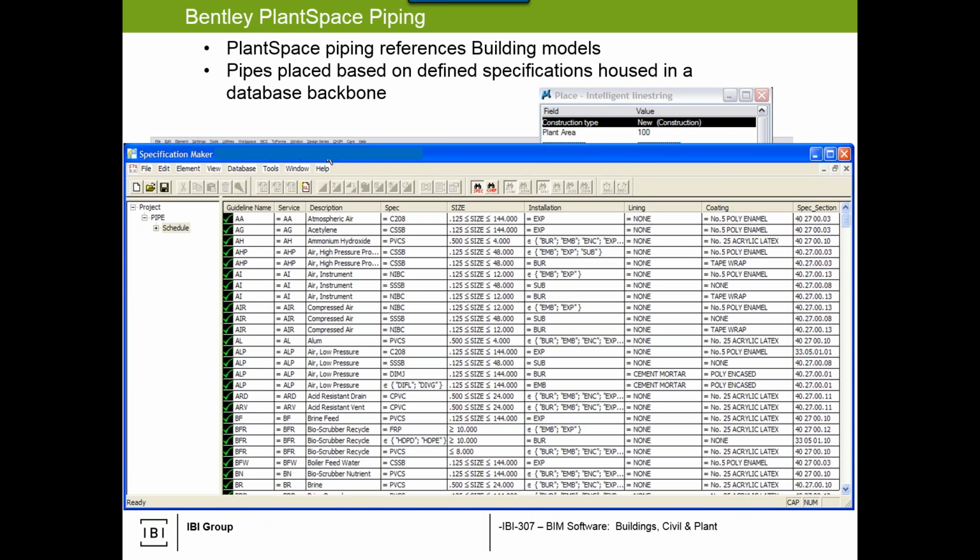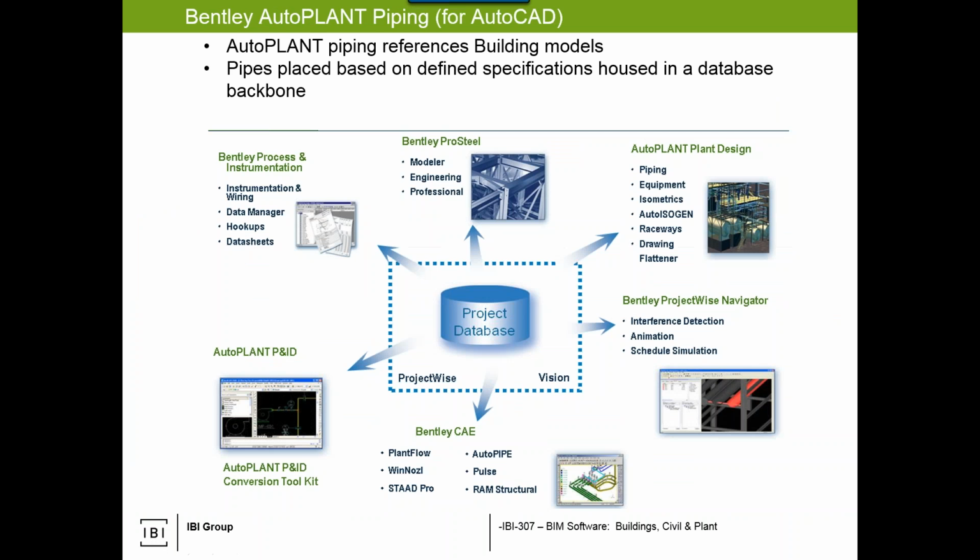And it takes time to build this. The vendors give you a really good starting point, thank goodness, but this is the complexity. You can see the limit of size. So if I pick this, this is what's flowing in the pipe, that's the size limit I have, and then there's restrictions on what I can place. So that's the beauty of the plant software, but it also could drive modelers a little crazy because they don't have the freedom to place anything.